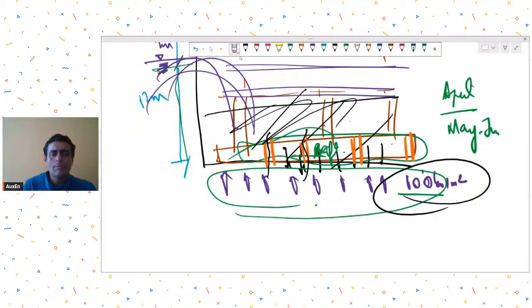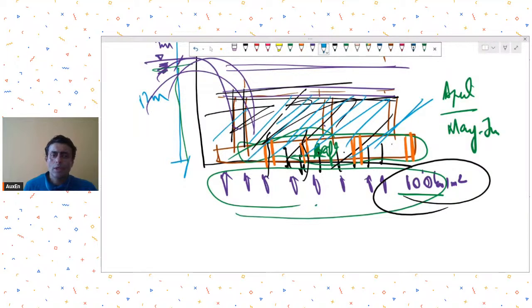The other way is what people do: let's say they had constructed one basement, they will just fill it up with soil and check the stability so that the raft does not get uplifted.